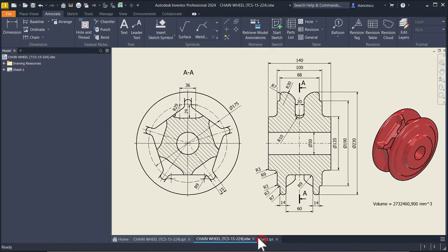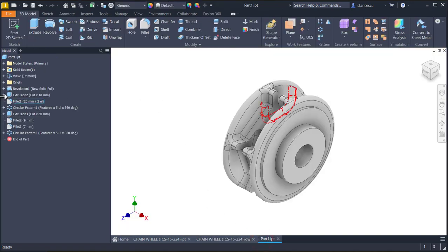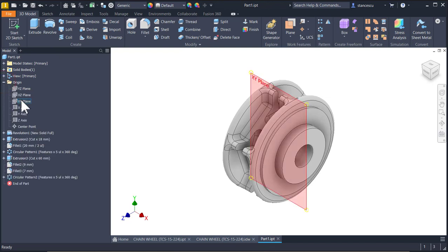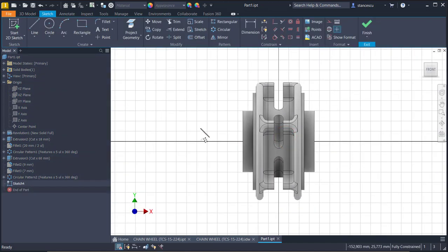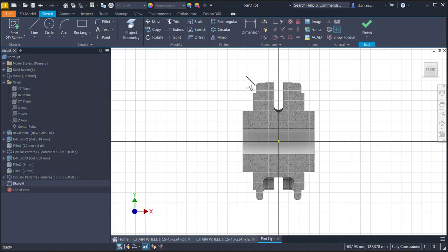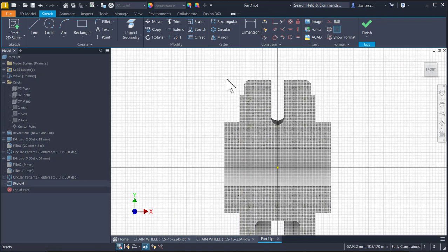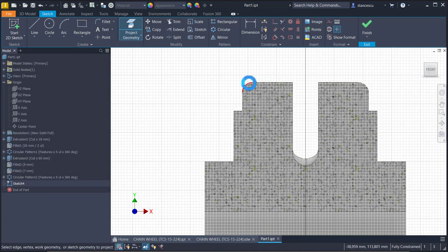Good. Let's do this. We use the plane XY for a new sketch. F7. Project this arc and this face.